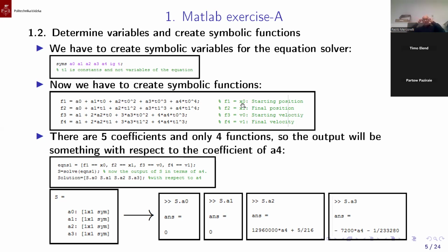This means, remember the concept which I tried to clarify last time. If I have 4 constraints to be optimized, we need to parameterize the trajectory using at least 5 coefficients. Because we need at least 1 coefficient free to optimize. Because if I don't have something free to be optimized, I have just a fixed trajectory, a fixed velocity, and in this sense, a fixed acceleration.